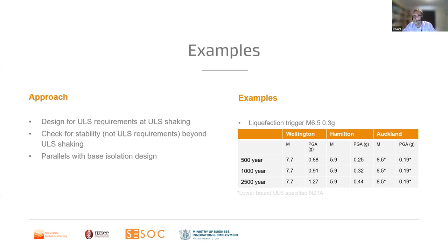Then the Auckland example. In this case we wouldn't expect liquefaction even right through to the 2,500-year event. So liquefaction affecting the building is considered quite unlikely. So in this instance, the project team once again could report to the client on the cost benefits of shallow foundations versus piles, and provide a recommendation, and the client could well select to go for the shallow foundations.